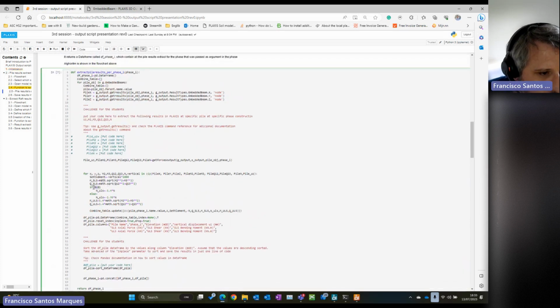Then I'm putting here a function in which I'm saying, if my actual force is in compression, which is negative, since in Plaxis negative means compression and positive means tension, and I want my ULS actual force to be factored by 1.4, then what I'm doing here is just multiplying by 1.4. And again, the sign convention I want to use in my processing later is to assume that compression is positive and tension is negative, so it's opposite of Plaxis. Therefore I multiply by -1.